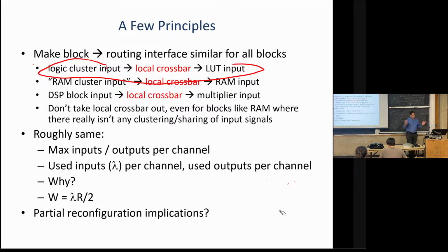So there's not a huge downside, but there is some, and it helps the CAD tools. End users usually don't really care about the CAD tools. They just wonder why you have these extra LUTs. They don't know that the CAD tools would probably have had lots of unroutes otherwise.